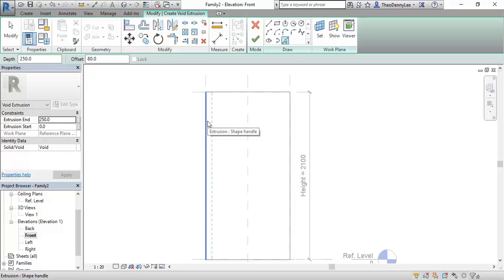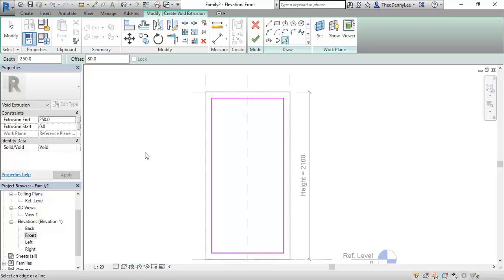No, you want to be making the extrusion. Unpick. How do I unpick? Just, have you clicked on it? Yeah, I clicked on it. Just undo. So now I'm going to press Tab, and again, you can see it's chained in this direction. So I can then just click, and it's going to offset in from all four sides.